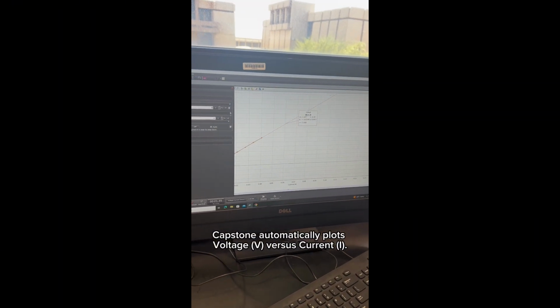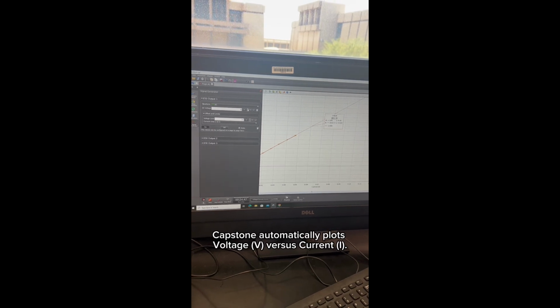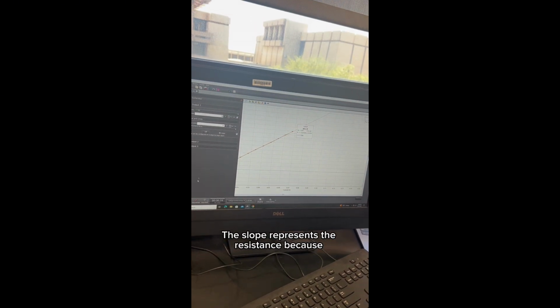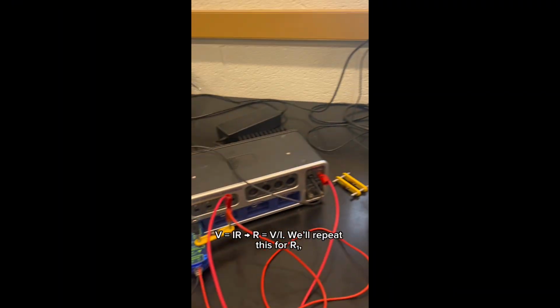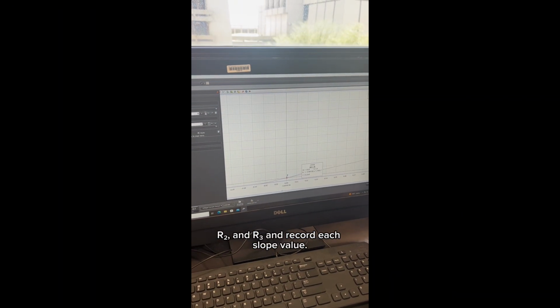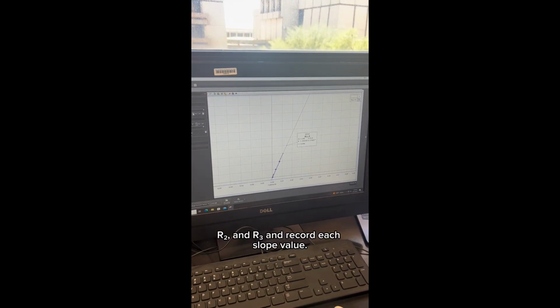Capstone automatically plots voltage V versus current I. We apply a linear fit to the graph. The slope represents the resistance because V equals IR gives R equals V over I. We'll repeat this for each resistor and record each slope value.